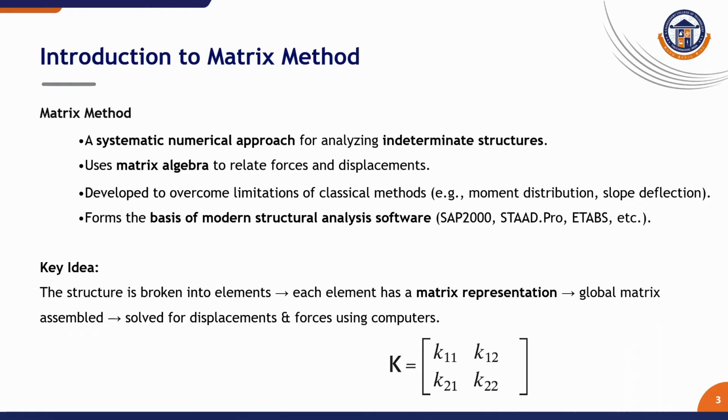Today, the matrix method forms the algebraic foundation for industry standard software like SAP 2000, STAAD Pro, ETABS. The core idea involves discretization of a structure into finite elements, each represented by a matrix, assembling these into a global matrix system, and solving for unknown displacements and forces computationally.